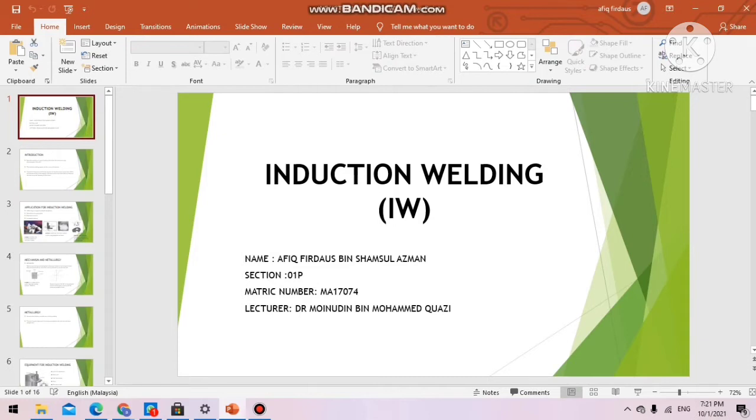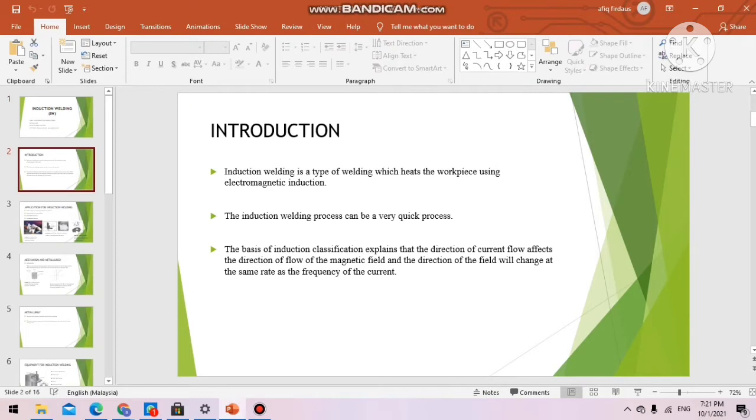Today I want to present about induction welding. Introduction: induction welding is a type of welding which heats the workpiece using electromagnetic induction. The induction welding process can be a very quick process. The basics of induction explain that the direction of current flow affects the direction of flow of the magnetic field, and the direction of the field will change at the same rate as the frequency of the current.